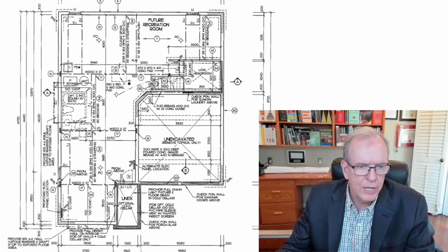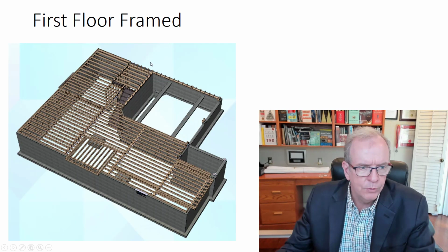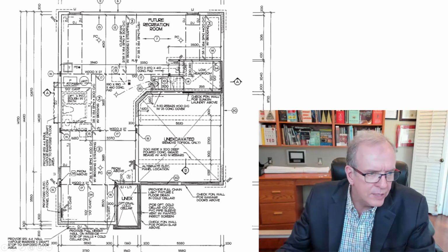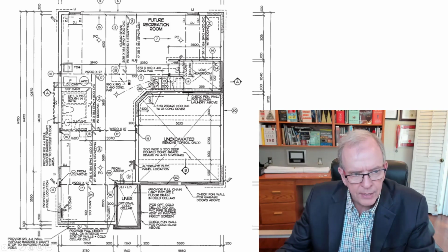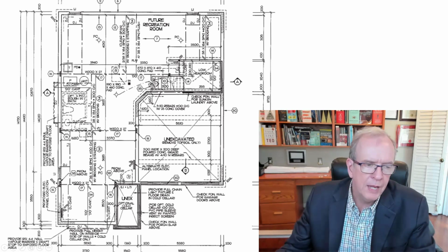And just to rotate it a little bit and give you another view of it, here you can see the cantilever joists. And the cantilever joists, they say DJ, that stands for double joist, TJ, triple joist, right? That's going outward. And by building code, if you're just using Part 9 in Canada, they have to go back at least 6 times that distance that they go out, or they have to be engineered specifically for that purpose.